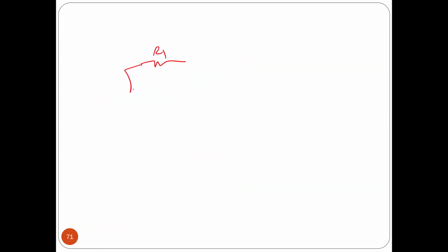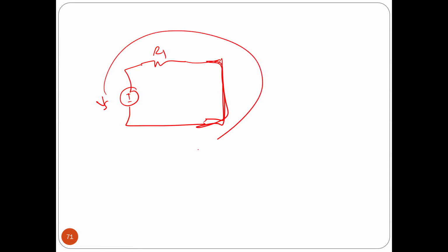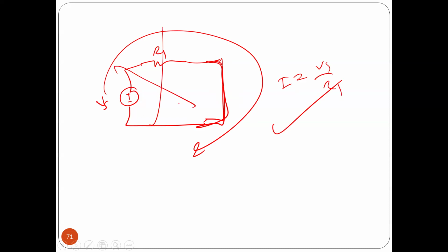I think what I did, I didn't draw the circuit, and when I was looking at it, I just made the short circuit. That's my fault. Yeah, because you need to show me. Now you have R1, you are going to cancel this one because the switch is open. And now you need to show me the inductor here is actually a short circuit. By this way, the current I have here should equal VS divided by R1. You didn't give me the circuit, but at least you gave me a formula. But for Norton, you didn't draw a circuit, you didn't even give me a formula.